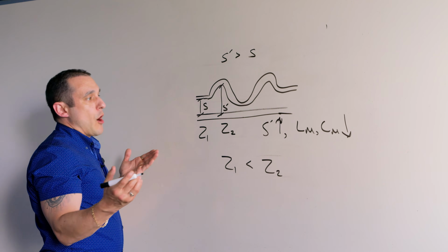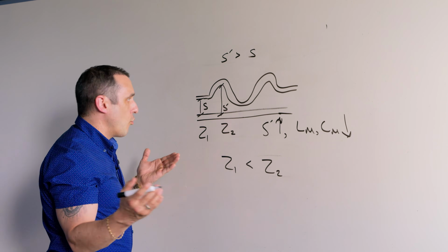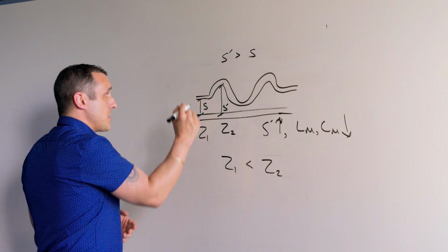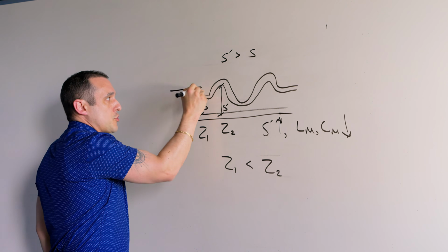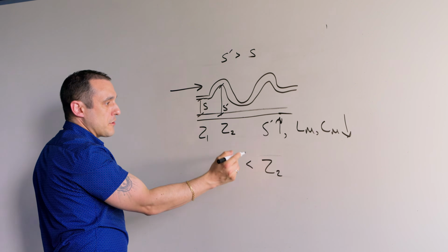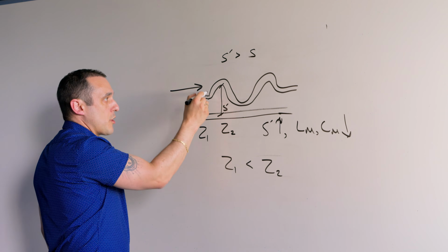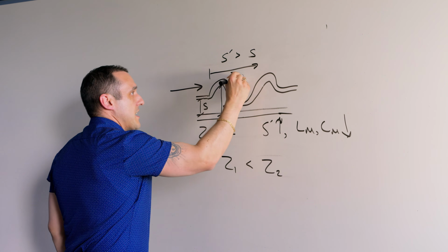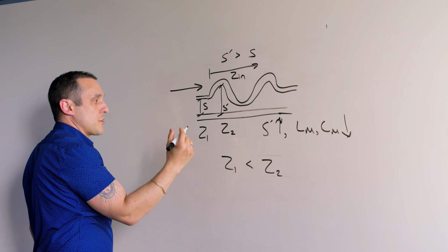So you might be wondering, okay, that's all good and well, but why does that matter for signal integrity? Well, it matters for two reasons. The first reason is that if you have a pulse traveling in right here and it encounters this length tuning section, it encounters an impedance discontinuity along this part of the route. So there is an input impedance, we'll call it Zin, looking along the length tuning section.